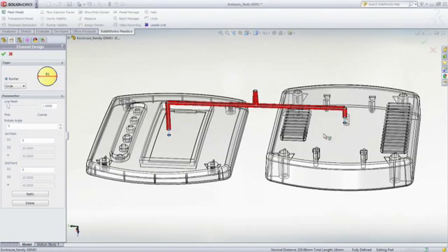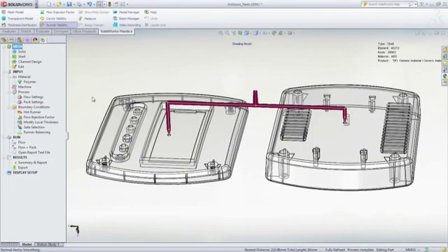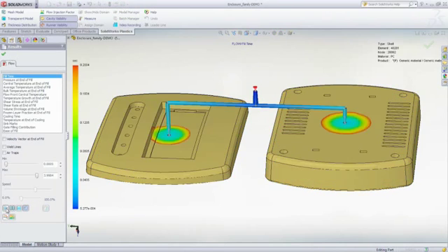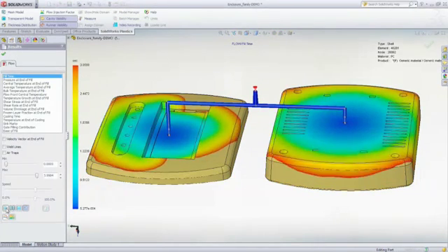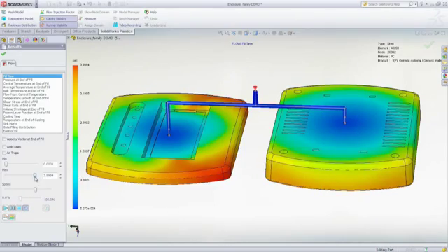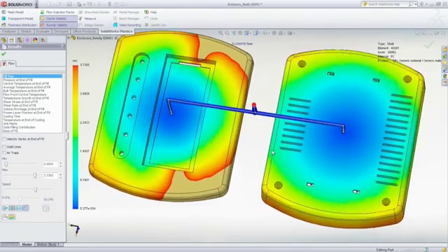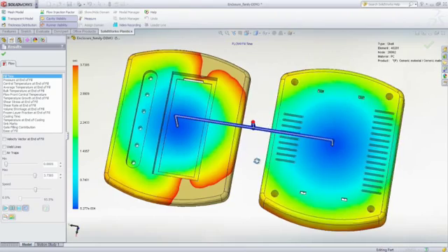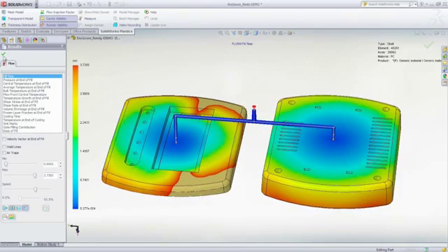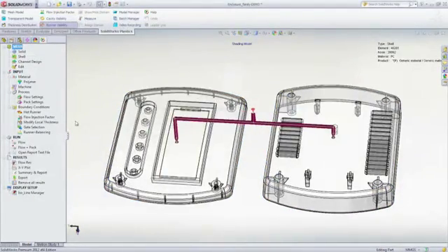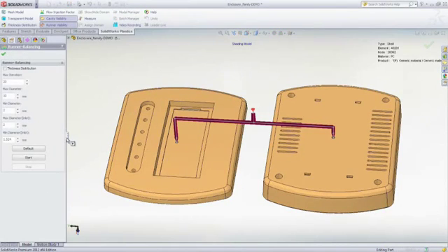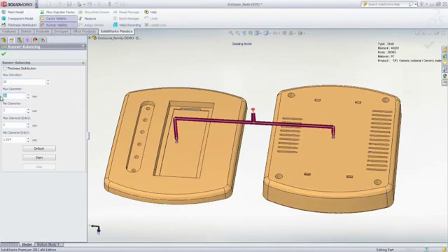However, an additional challenge is introduced because when you mold two or more parts of differing geometry in the same mold, your goal is to get all the mold cavities to fill at the same time. And this can be virtually impossible to achieve without the use of SolidWorks Plastics simulation. The good news is that you can perform a runner balancing analysis in SolidWorks Plastics. This is a multi-iterative analysis with the objective of filling multiple cavities of differing geometry at the same time.